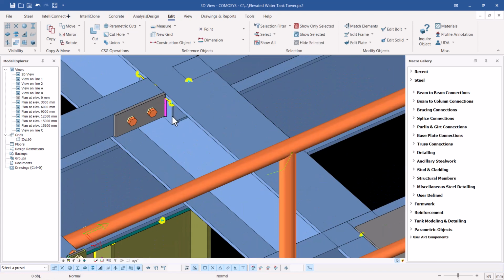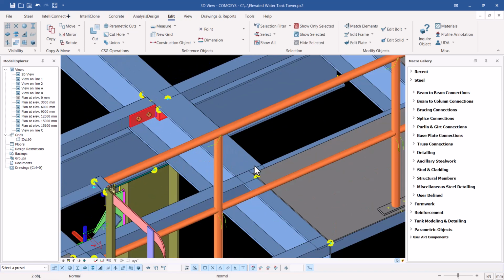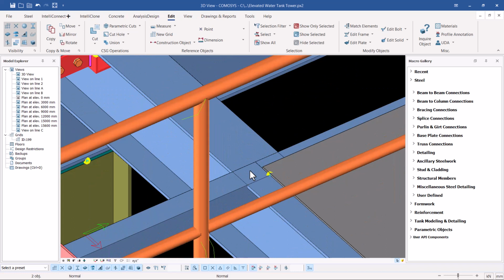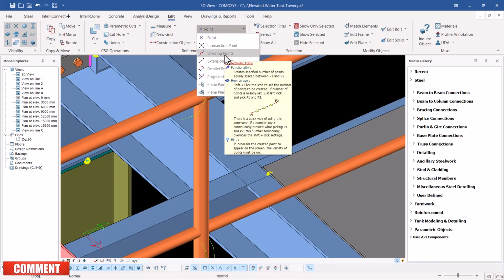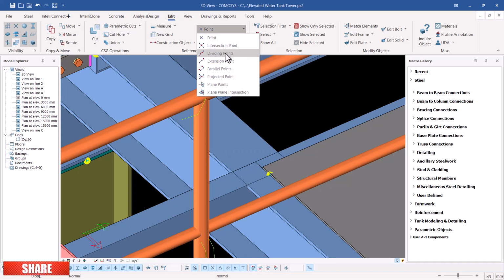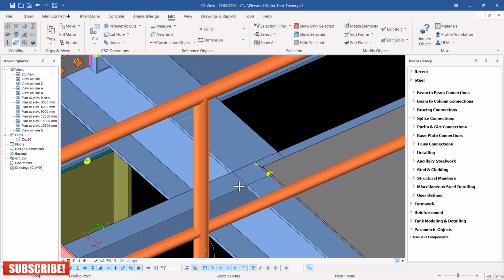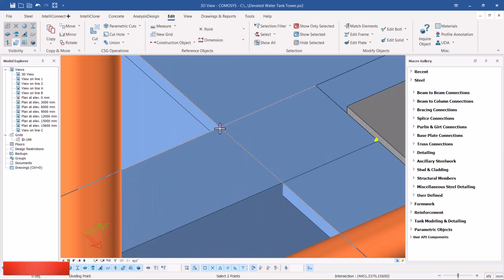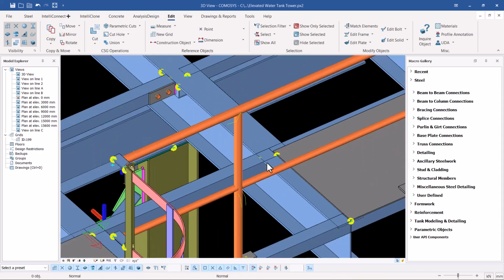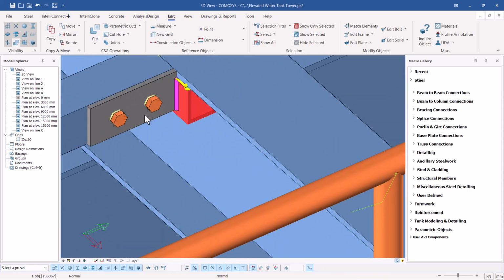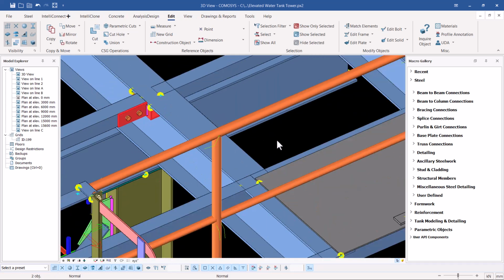And I'm going to select this, press Control and select that. And I want to copy this here. Since I'm not able to snap at the midpoint here accurately, to create an accurate snapping point without any doubt, I'll come to this point and define or place a midpoint right there. So the moment I create a midpoint there, I'll be able to select this, press Ctrl and select the parts you want to mirror or copy.